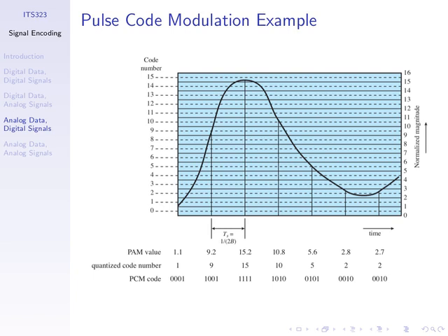Note that what I did is I drew them between 1 and 2. So if we had 1, I drew between the mark here, 1 and 2. That is, this is level 0. This is level 1, or the code number 1. And I simply produced an output in the middle of that level, at this dashed line. If we could map this diagram to here, I drew the output where the dashed lines were. If I had 1, I drew it here. 9 here, 15, and so on.